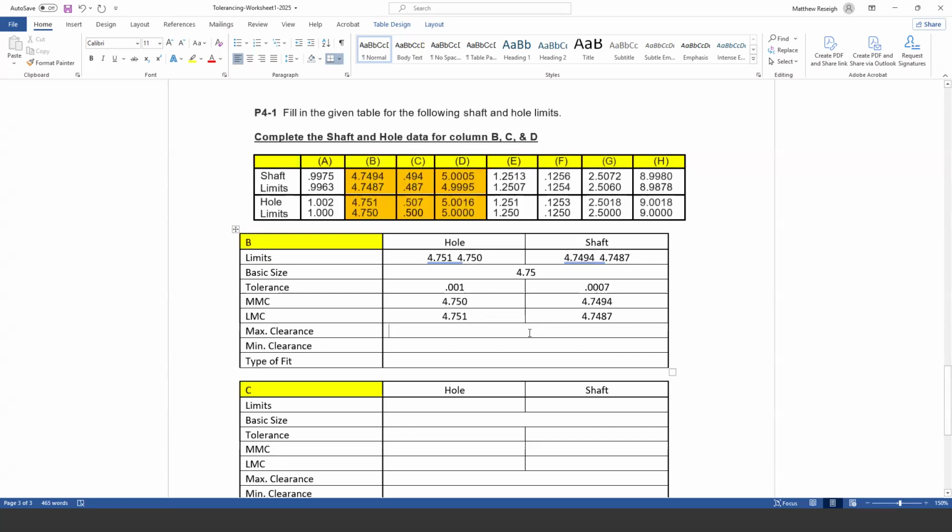The reason why somebody like a drafter might use this is I might build my own little spreadsheet so that I could know how to build my dimension style on my drawing. This might help me put together what I need to know, like the tolerance plus or minus. So charting like this, or figuring out some of these dimensions, might help you build a dimension style in the future.